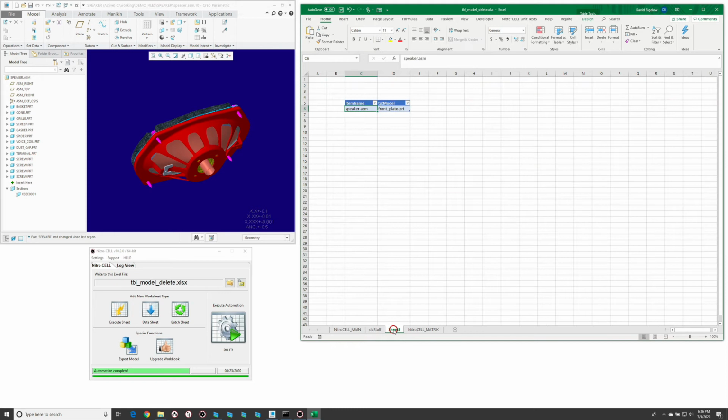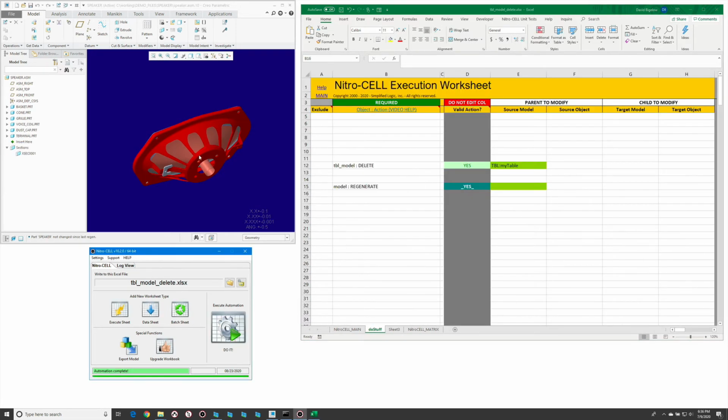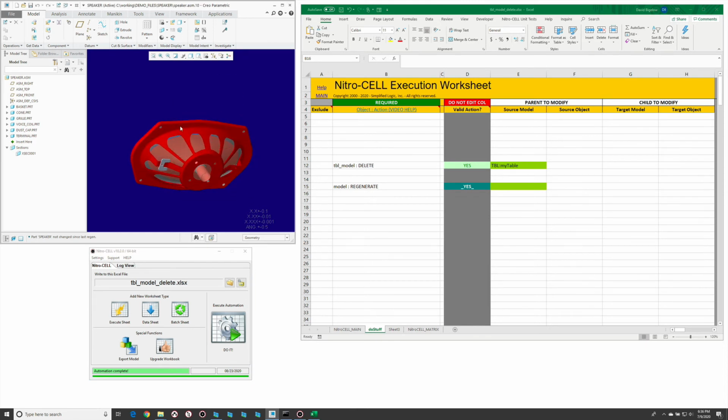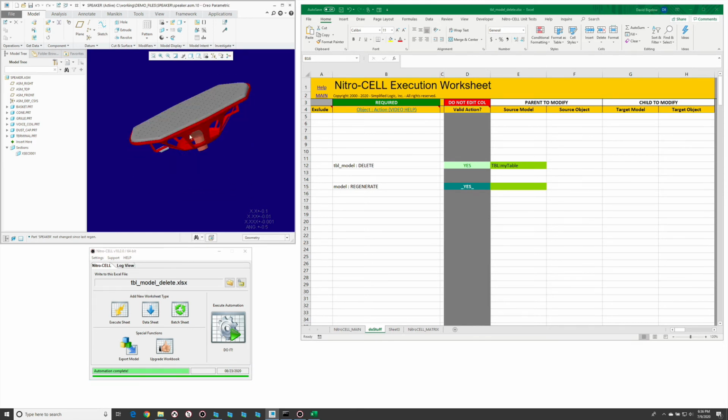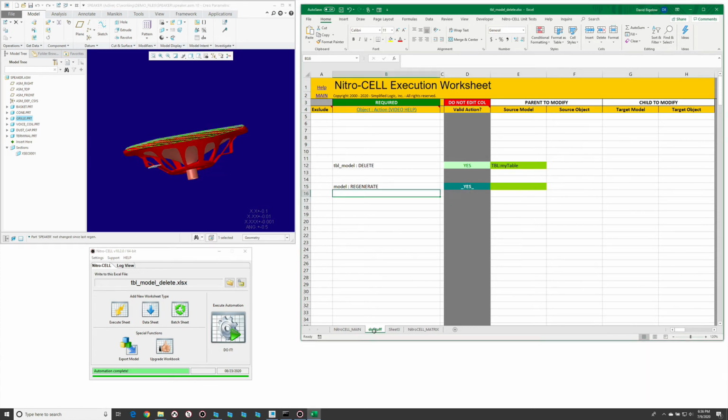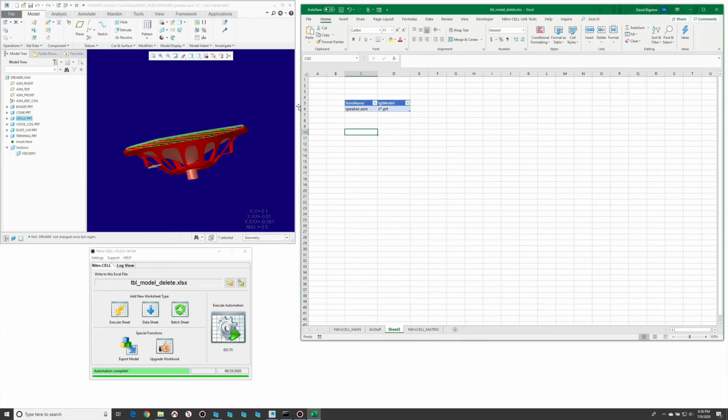So let's push this a little bit further. We can also use wildcards with this. If I wanted to get rid of anything that starts with s.prt and run that, you'll notice that it has removed not just the items that match that, but also any items above it that were dependent on that. So we had a grill here, and we also had a gasket on top of that, and there was a screen in between that was dependent on the placement of those things. So it actually got removed. The wildcarding is quite handy.